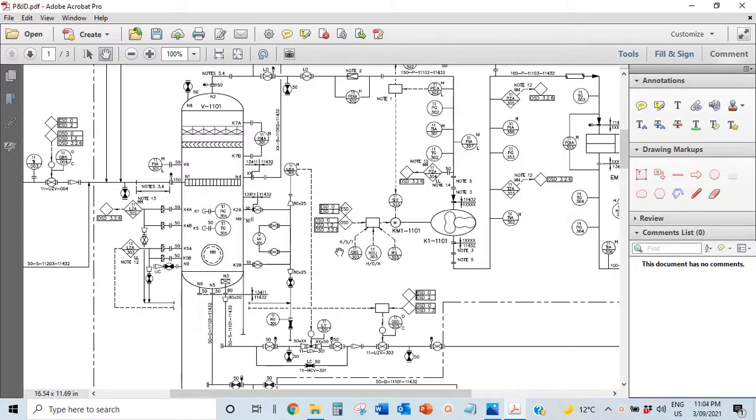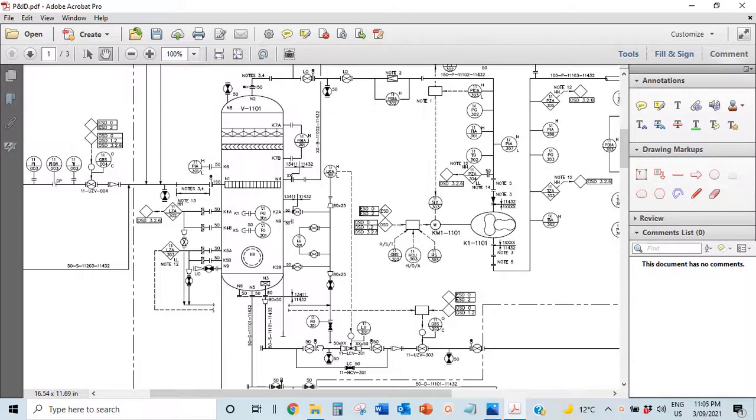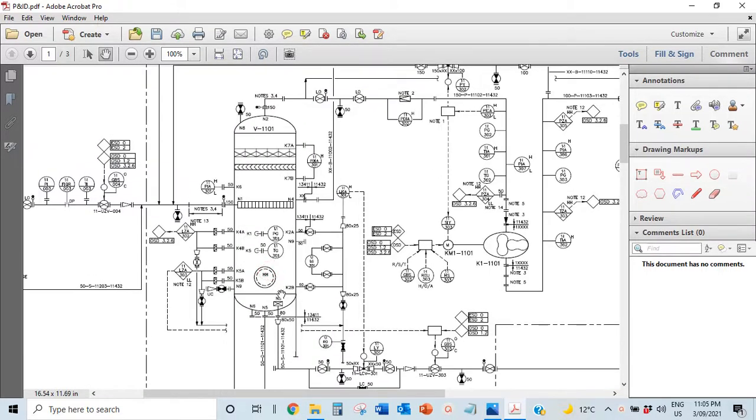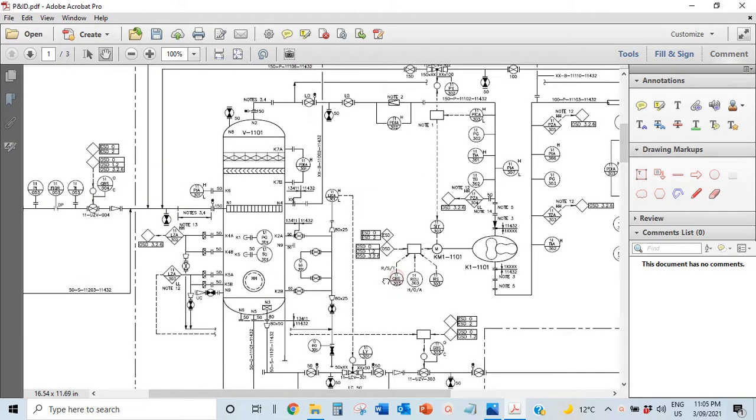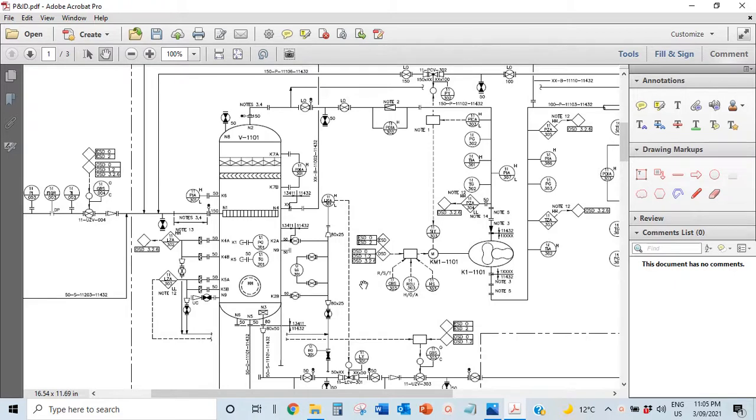We want to know the risks associated with every single piece of equipment: the valves, the vessels, the fans, the compressors. What risks do they pose, what is their failure rate, how hot is it? We want to know how long the liquid or gas trapped in here is going to burn, because we're going to use all this in our simulation.